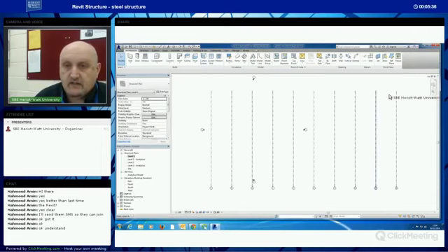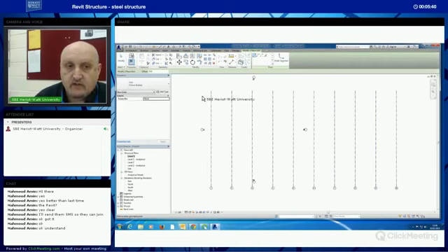I'm going to put in half a dozen horizontal grid lines. The very first thing I have to do is remember I'm creating intersections here because I'm going to use these intersections to place things on. And I have to make sure that I make the intersection. I don't start in the corner here. That's kind of the intuitive thing to do, but please avoid doing that.